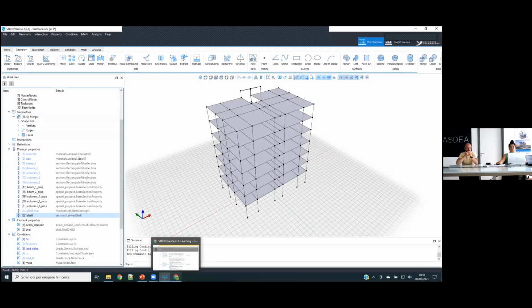And the same concept can be seen in that e-learning course, because in that course I was modeling a shear wall with a face, with a surface, and then the two boundary edges were modeled as fiber beam sections. So it is completely the same concept. You can see the shell in the middle and then the boundary edges, which are beams. So you can just look at that webinar and apply the same concepts to the slab surfaces of this model.